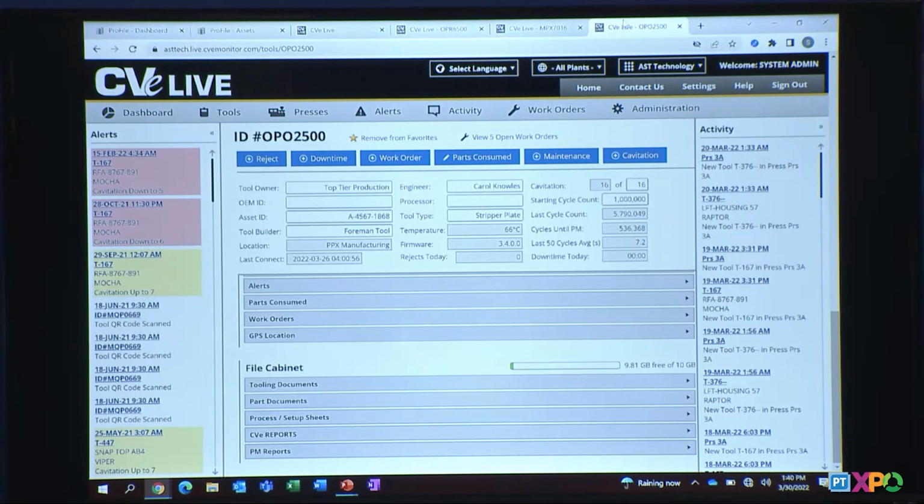Another aspect of mold monitoring is really what's going on inside your mold. Cooling is about 60% of a typical mold cycle time. So understanding what's happening in that 60% of time, there's a lot of benefit when you're looking at continuous improvement activities, reducing cycle times, trying to reduce defects, and scrap.